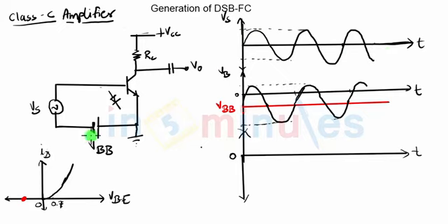When you add negative DC signal to the sinusoidal signal, it will shift down by a level equal to the negative DC signal. So you can see the waveform which I have drawn in the second plot, the black line will be nothing but the overall voltage generated on the base of the transistor. You can see the first waveform is shifted by the amount equal to VBB.